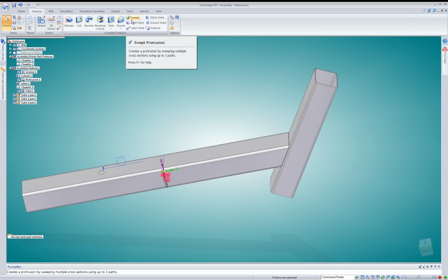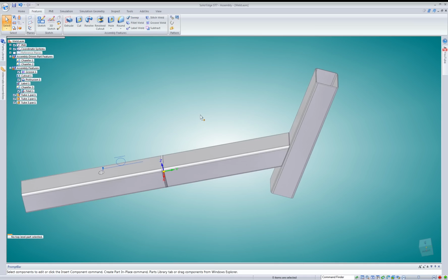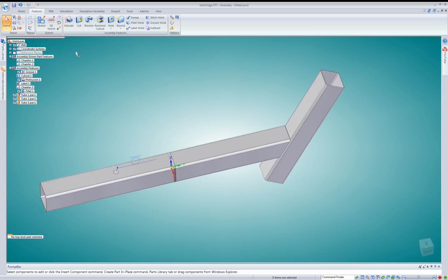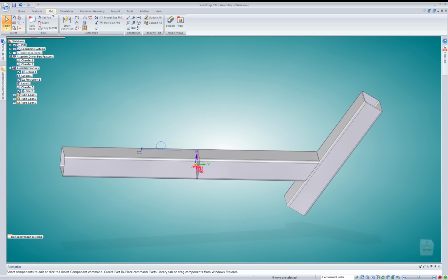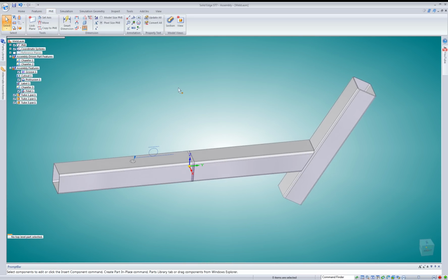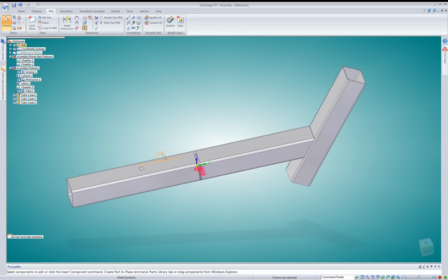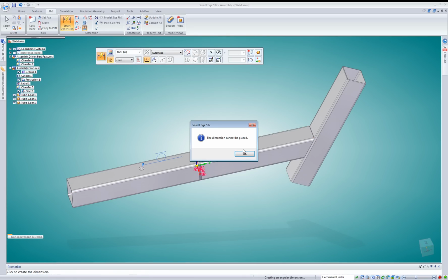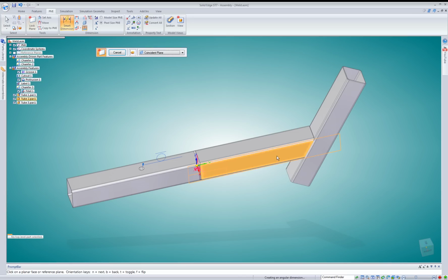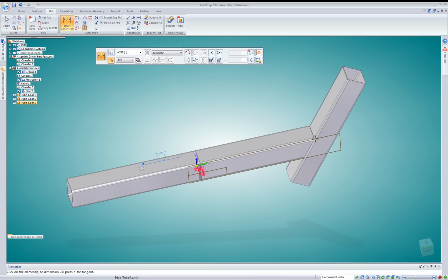Again, our cuts, the sweeps and lofts work the same way, where you can actually sweep a protrusion or sweep a weld bead through a feature. And the last thing we can do as an assembly post-treatment feature is create some PMI geometry. PMI geometry is product manufacturing information, and that was the weld bead that I actually created here. And of course, we can also create all our assembly dimensions. So if I wanted to retrieve my dimensions from the assembly, I could take my time and go through, and place.